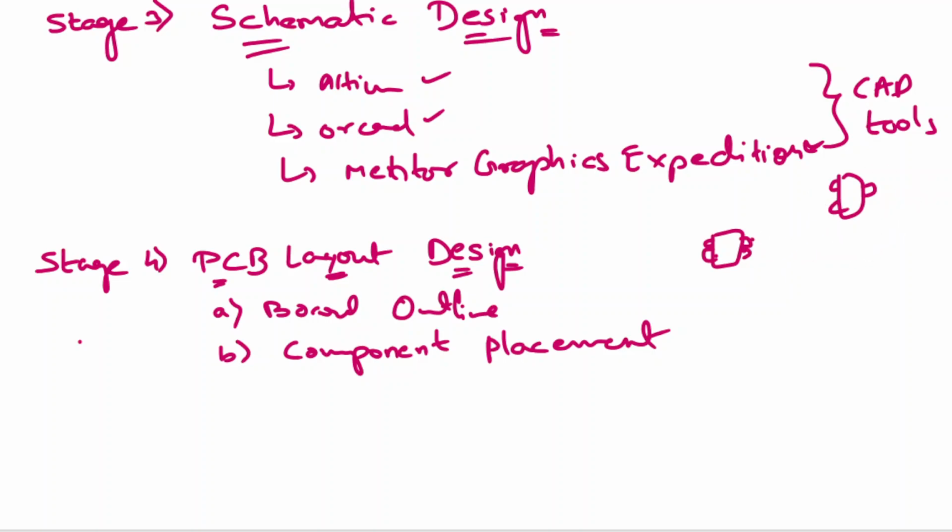Normally what people do, which is a big mistake, is try to place all the critical components first, and later place the non-critical components. That is fine, but doing that they forget what is the minimum length required between placing those two components. Say you are placing these two components, and for example, now another component is required here.